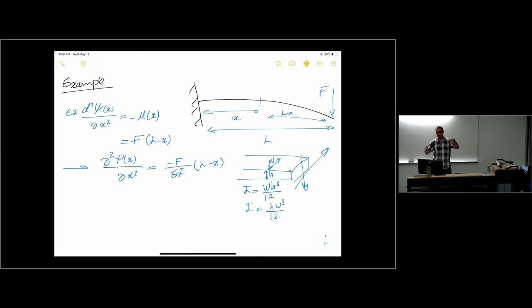So I expect the moment of inertia to be linearly proportional to that width. On the other hand, if I make this twice as thick, it is going to be much, much more stiff, right? It's not twice as stiff, it's significantly more stiff. And just do it with two rulers, on top of each other or side by side, if it is not convincing enough, if you have a hard time imagining it. If you put two plastic rulers side by side, same dimensions, they become twice as resistant to bending.